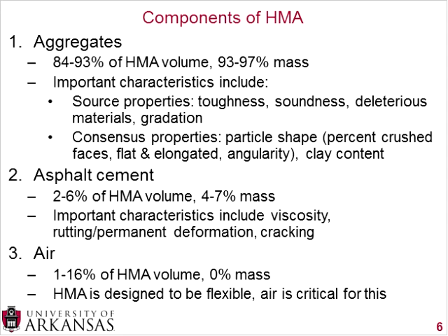And then finally, the third component of HMA is air, and that's anywhere from 1 to 16% of the volume, depending on the mix type, depending on how dense you compact it in the field, all sorts of variables. And then a question that I always like springing on students is, what would the mass of air be in any mix? And of course it's 0% mass, but that is something that you do need to keep in mind. It takes up a lot of volume, but when you get into the nitty-gritty of mix designs, at the end of the day it doesn't have any mass. So that's just something that you have to look out for.